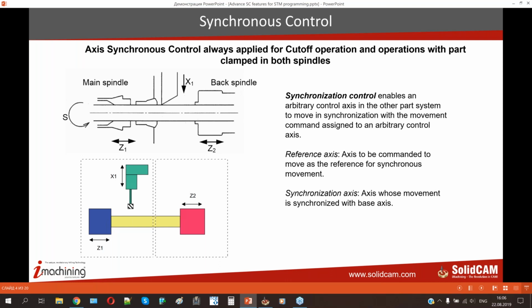The first rule is determinacy. A CNC controller can't have 2 Z or X axis movements in one line of program code because it ruins determinacy and the machine is confused about what you mean with such a command. If you ever operated a one channel mill-turn machine with sub-spindle, you should know that the Z move of the turret is never performed with the Z move of the sub-spindle in one line of the G-code. You can do it only step by step and in 2 different lines.